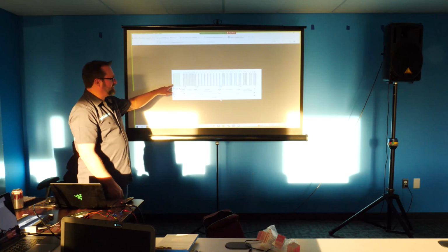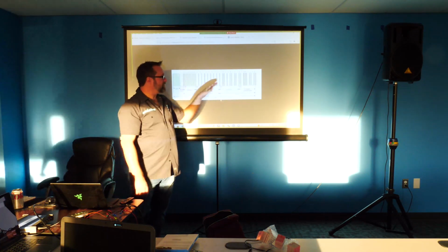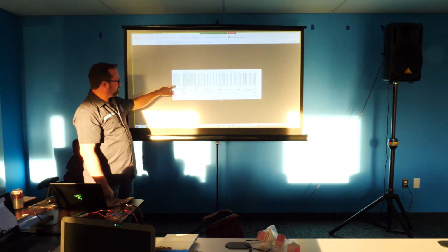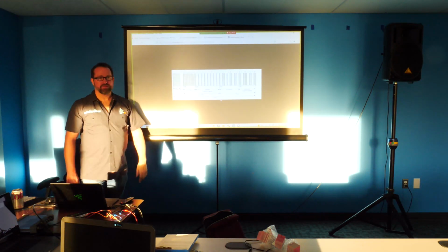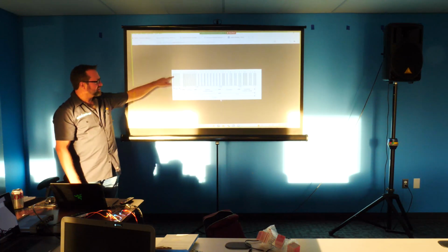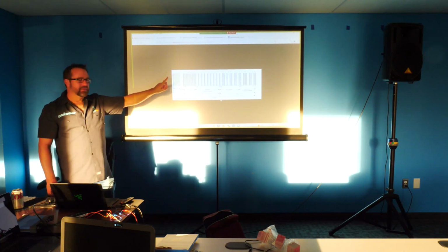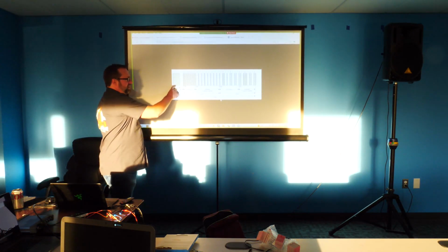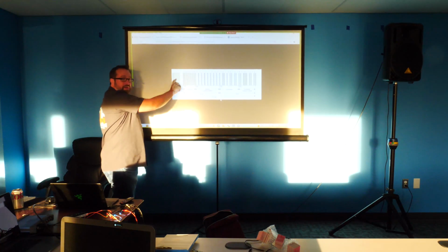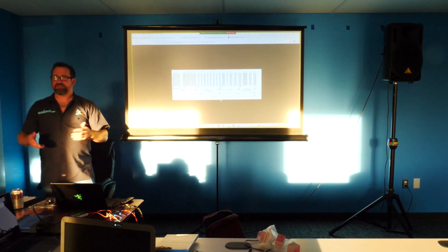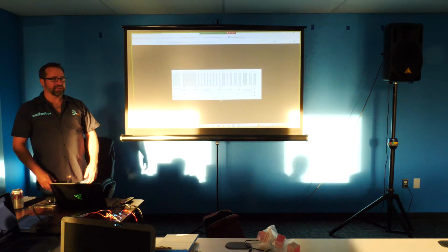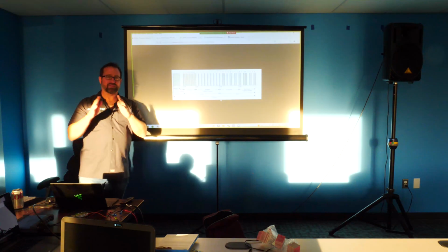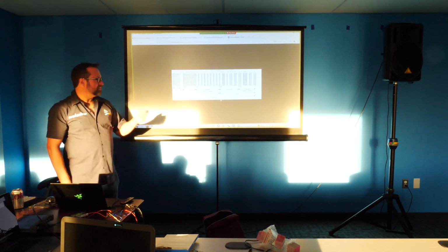So this is what the actual IR codes look like, this is what the waveform looks like, and there's a header. What this means is that the IR, this green area, is when the IR is generated. Now inside this IR is a 38 kilohertz on and off square wave. One of the reasons they modulate is that there can be all kinds of light sources, and by creating a narrow filter around that frequency, they can filter all that out.